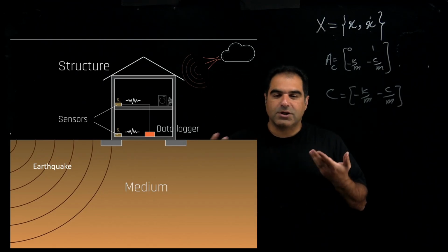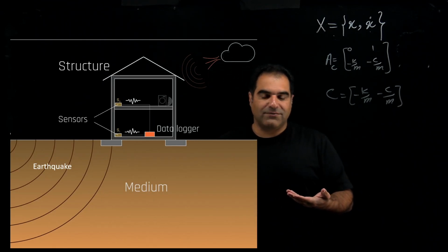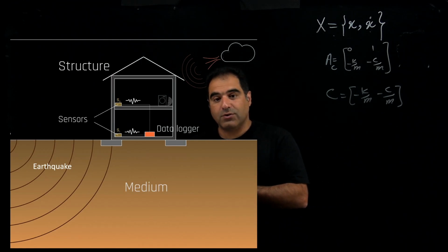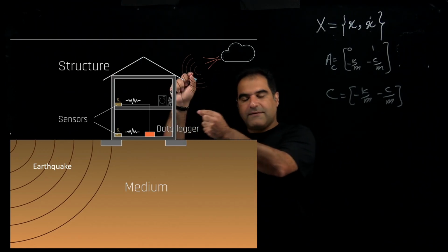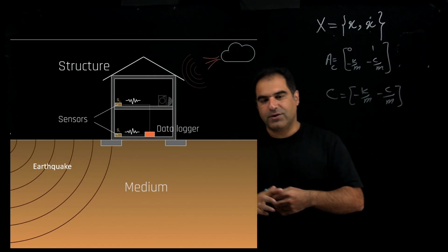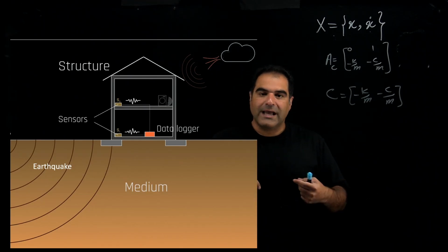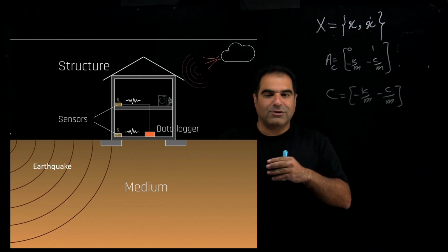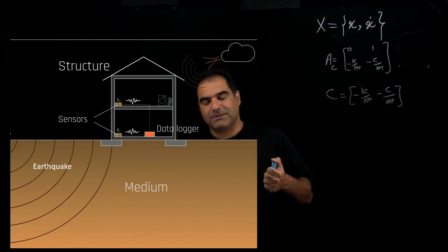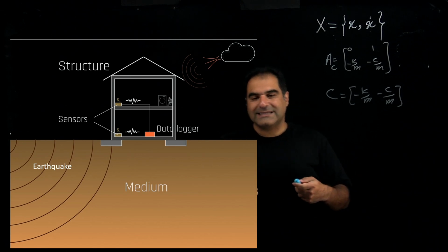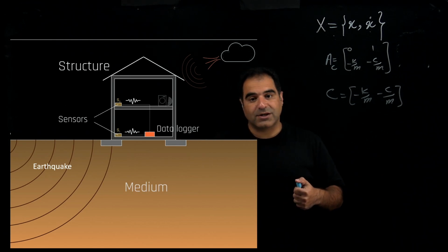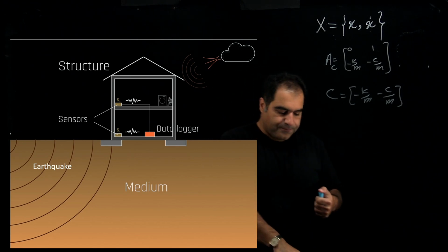What you do is just write the Kalman filter algorithm we had for a two-story building. Because you have the acceleration of the vibration on two different floors, you can estimate the displacement and velocity of vibration for each floor, and use the threshold you have to see if the displacement of vibration on the second or first floor exceeds a specific amount, the trigger level, or not.